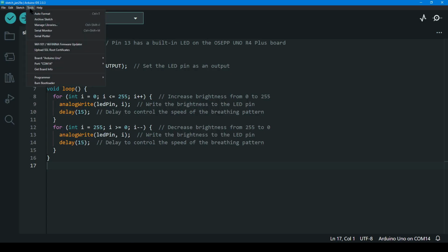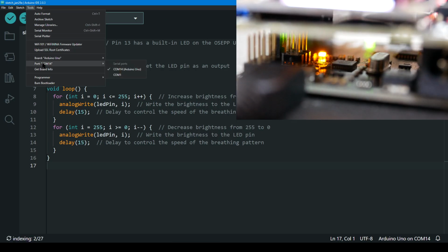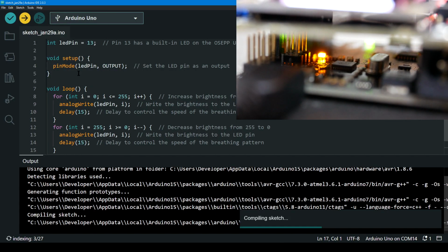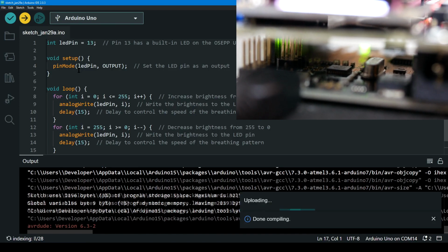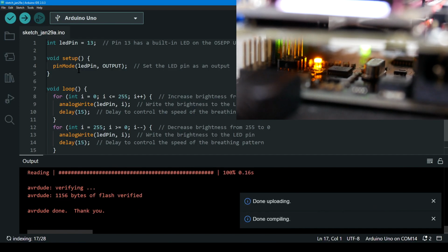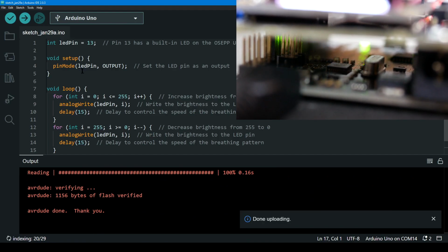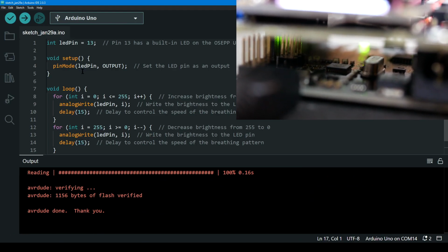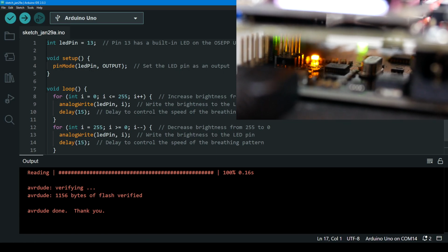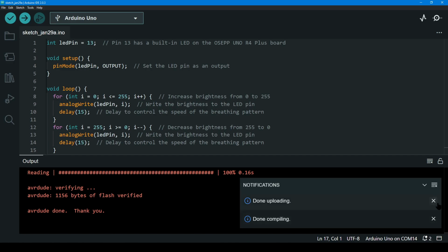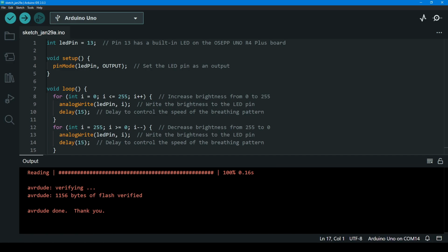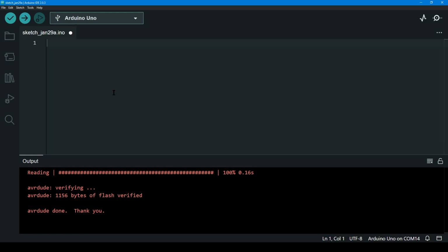The first test of generating that breathing pattern didn't exactly go well, but the LED is still blinking. This is what it did after uploading twice. So either this is the original programming, or I'll have to classify this as a failure. It is not often that I use the analog out function, because generally if I want this I'll use a digital to analog converter, or I will set up the PWM using the registers, because I normally like to use phase-corrected PWM instead of the default setting.